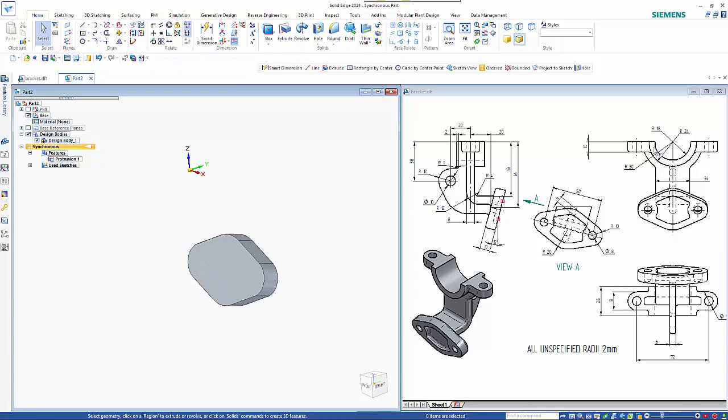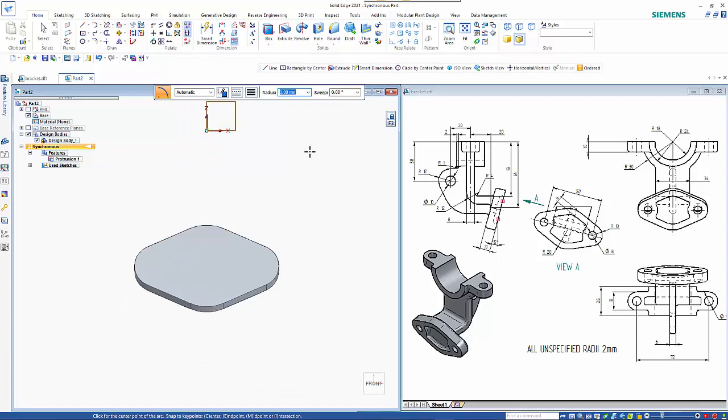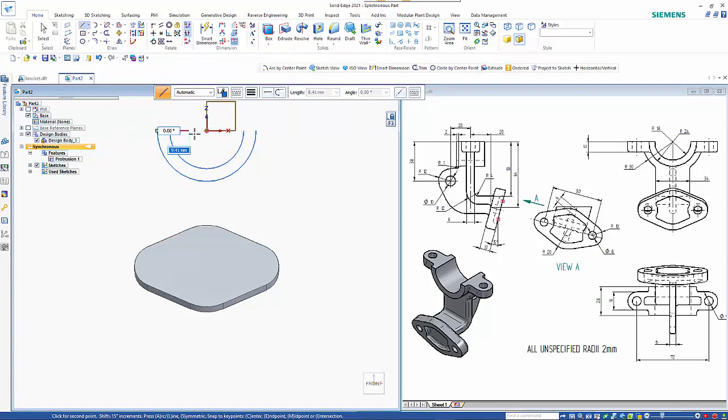I'm now going to create the piece up at the top. So I'm going to use an arc by center, again locked to this plane, and inner one is 18 radius, starting at the center, and just bring that round. The outer one is 24, again going 180, and then use the line command to just close off that. Right mouse click to start the new one, and that creates our closed region.